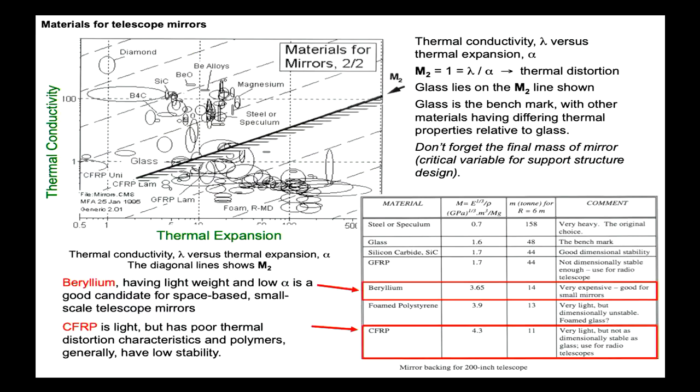Now, I did say that there's more to it than just the specific stiffness. Thermal expansion is important. Thermal conductivity is up there. And again, we can now cross-reference, and with the CES software it makes it a lot easier, but just for the here and now, the candidate materials can be cross-checked with something like this.